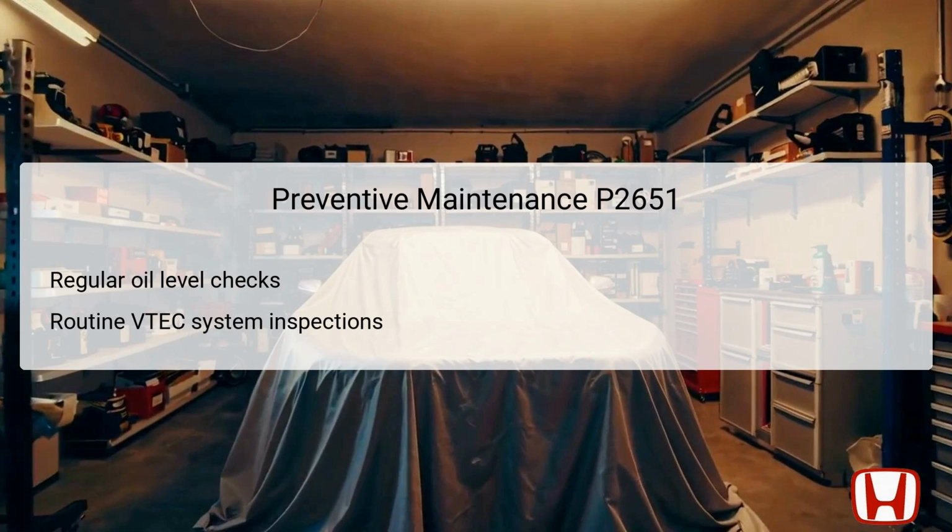Engine oil changes should adhere to factory recommendations and use quality oil to reduce wear and tear. Additionally, ensuring all electrical connections to components like the rocker arm oil pressure switch are secure can prevent intermittent failures. Regular maintenance strengthens both performance and longevity of the vehicle, minimizing the risk of future diagnostic trouble codes.